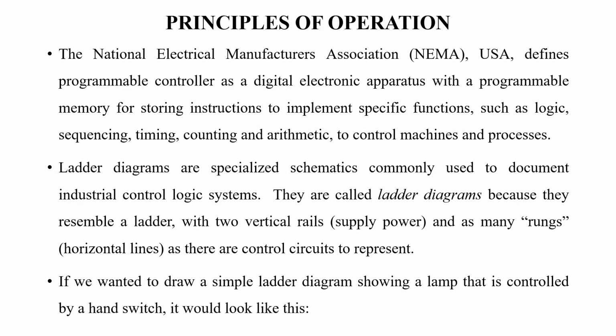Coming to the principles of operation of PLC, as per NEMA, the National Electrical Manufacturers Association USA, a programmable logic controller is a digital electronic apparatus with a programmable memory for storing instructions to implement specific functions such as logic, sequencing, timing, counting, and arithmetic in order to control machines and processes. Also, ladder diagrams are specialized schematics.